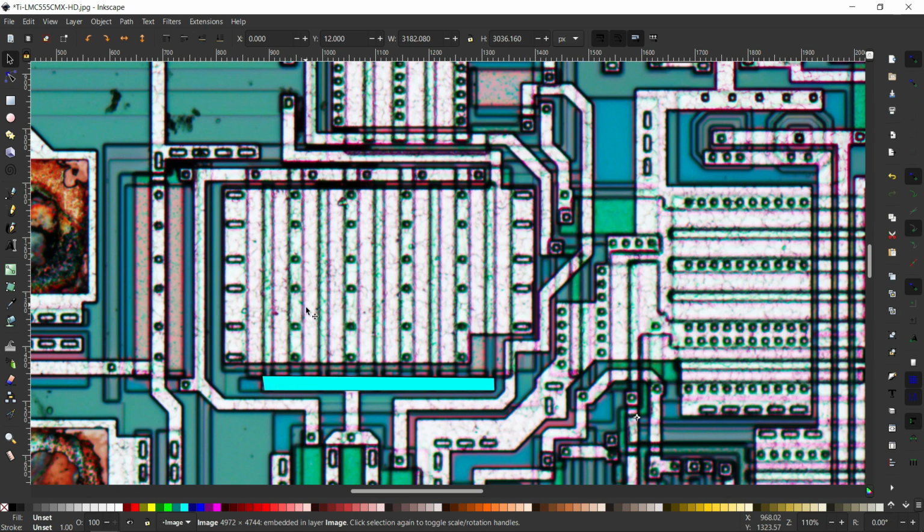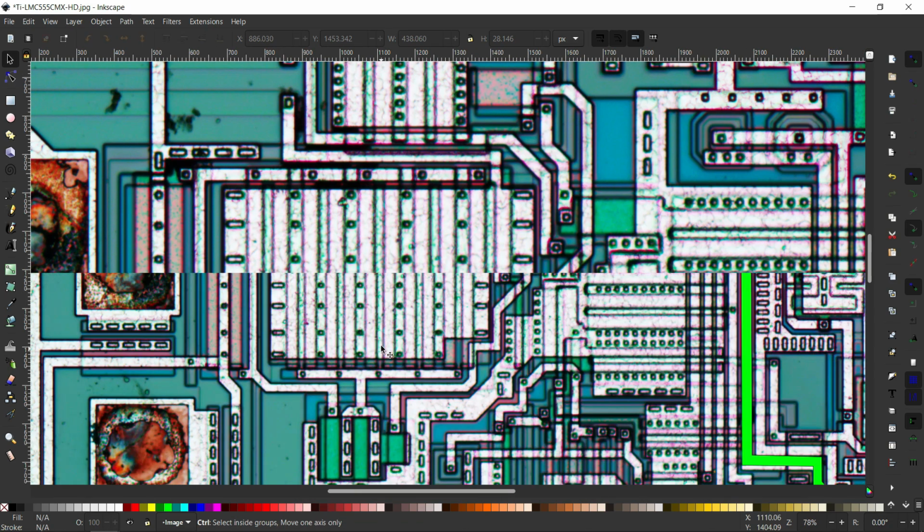Then in between they have a small line, right? All of those are source and drain connections. Here all the sources are connected to other wires with a single wider connection, and the drain they have taken as a tap on the top side. So this is the drain connection and the other one is the source connection. Easily we can do the reverse engineering for this, to see which kind of connection it is.